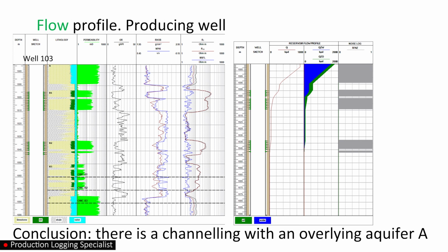In order for us to better understand what pressure should be maintained so that it will not cause a cement-stone fracture, I would also make a point-by-point test in the well that is about to be drilled, just to clarify what pressure we currently have in the overlying water-bearing formation, so that the resulting value is taken into account when calculating the maximum allowable bottom hole pressure to prevent further behind casing circulations.